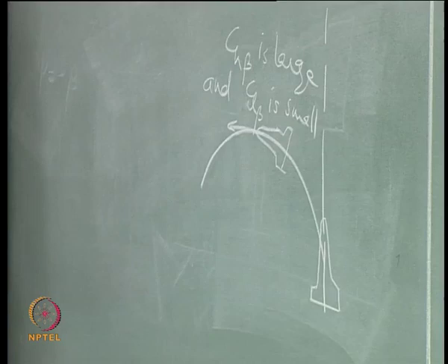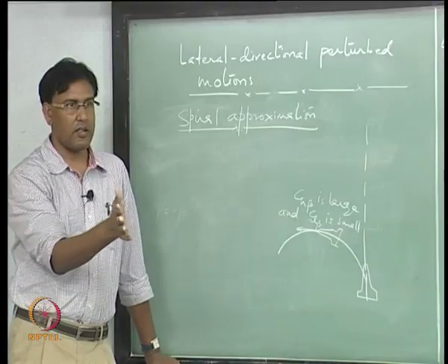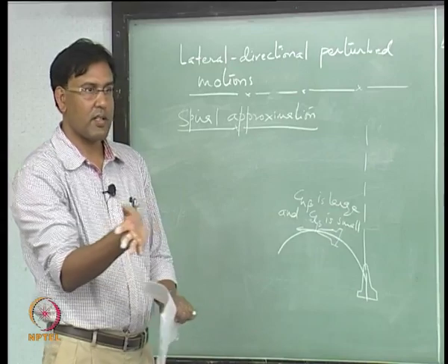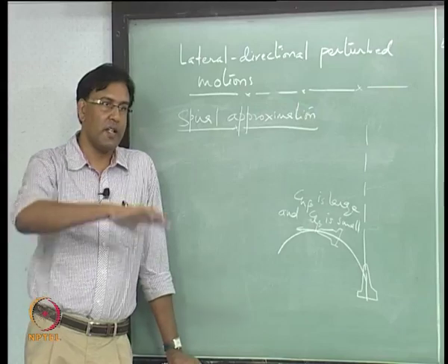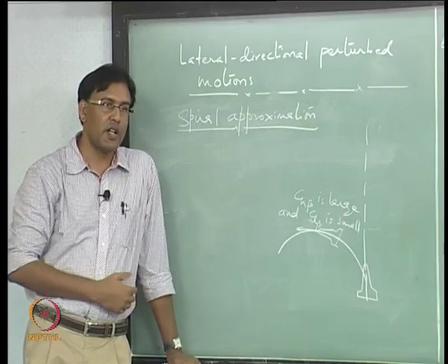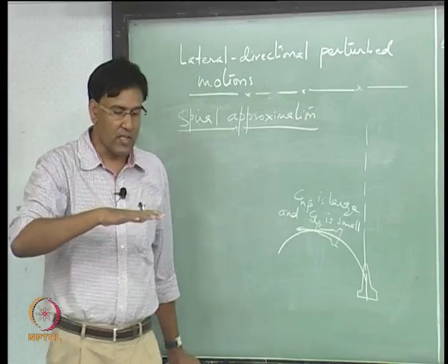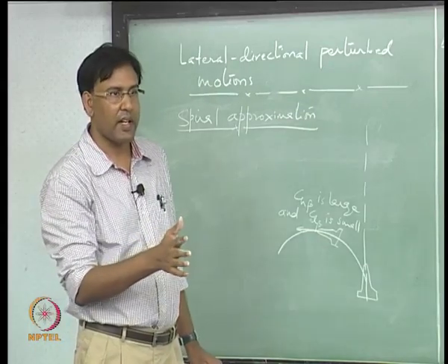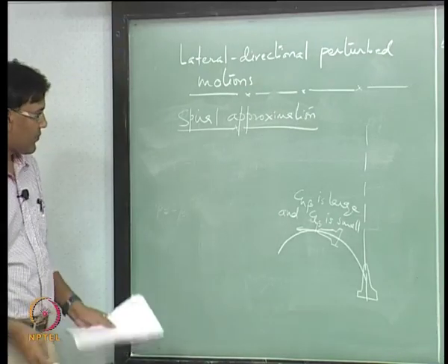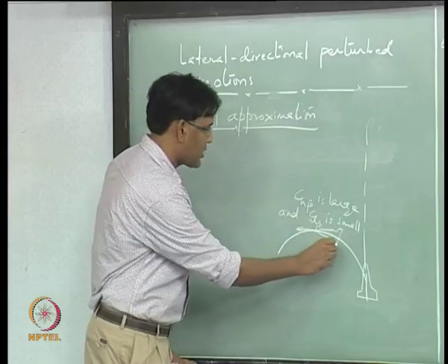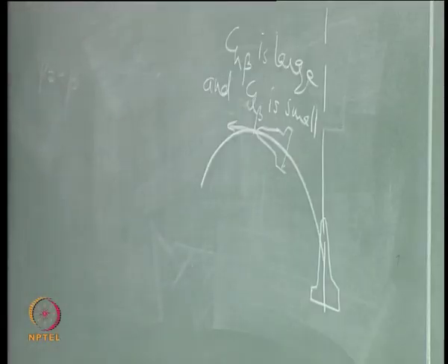okay. So, it is doing this and then starts, right, and also it will start falling down. Now, we have understood that, right. Whenever there is a change in bank angle, the lift produced will not be enough to balance the weight. So, it will start doing this banking and it is also going down, and that is the spiral divergent motion. Okay, in a critical case actually it can also take a dive, that is called a spiral dive.